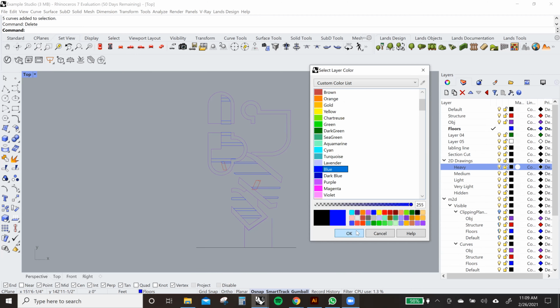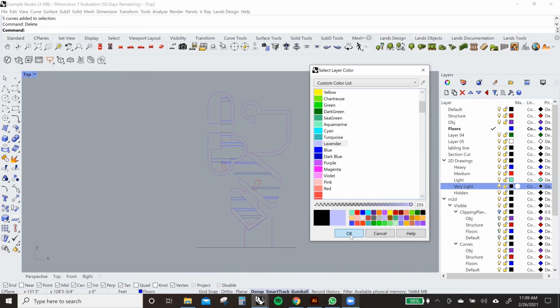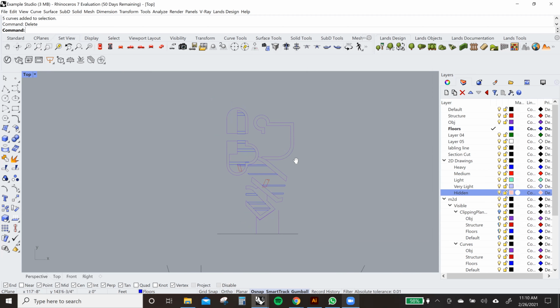So I usually change the colors of these, and this is something that I do across drawings generally, like across files. So I have my own kind of language that I've set up. And the reason I feel this is important is because once you start to have this hierarchy of colors set up in your mind that you repeat across files, you'll start to be able to visualize, through this very conceptual, technical setup in Rhino, what it's going to eventually look like when you bring it into Illustrator and it starts to have physical line weights to it.